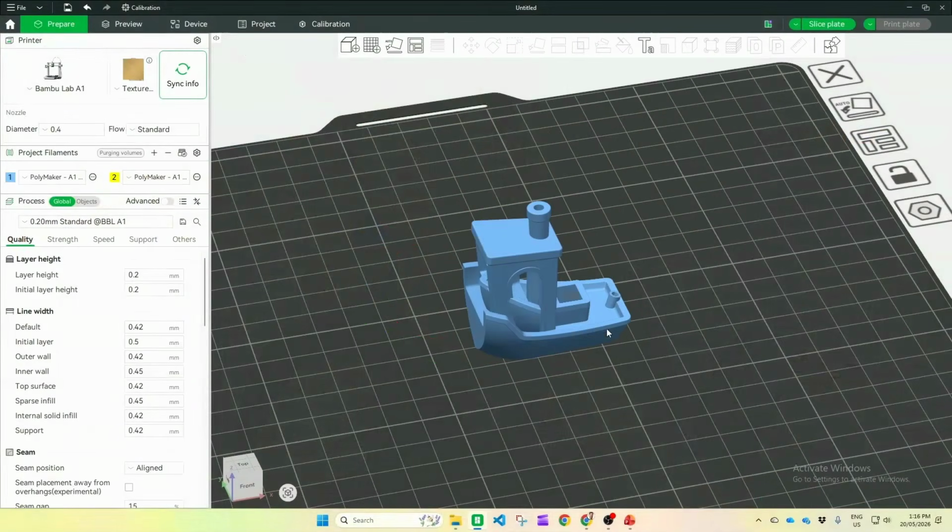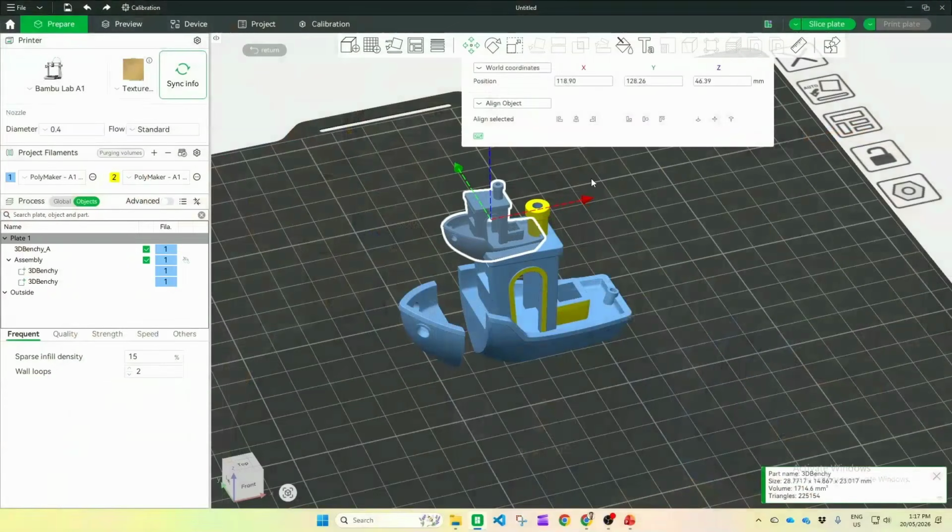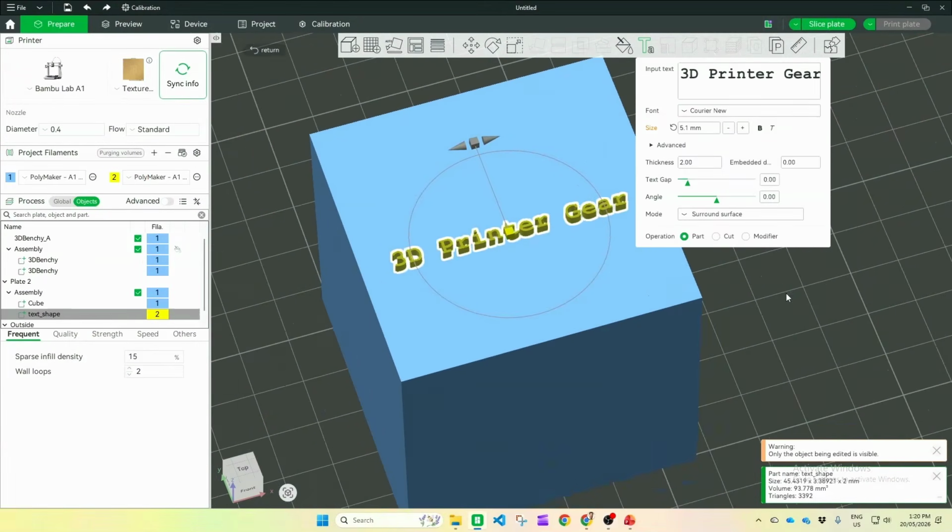Next, you can even modify your design in the slicing software. Continuing on with Bambu Studio, you can split a model into parts, you can color the model, you can add holes and negative parts, you can join models together, you could add text, you can change the size, you can use graphic files, and a whole lot more.